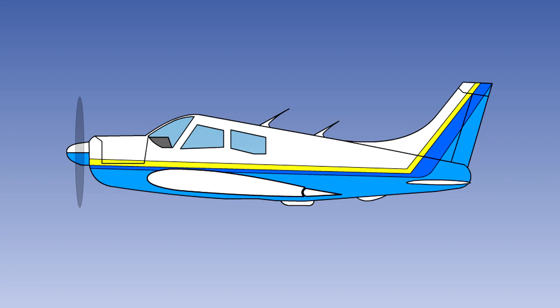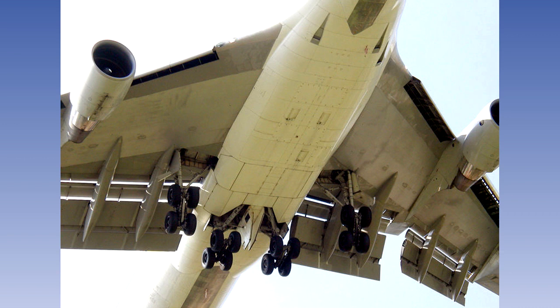The most popular type for light aircraft is the plain or camber flap, with trailing edge flaps, which are a combination of slotted and Fowler flaps widely used on large transport aircraft. This picture shows the triple slotted Fowler flaps on the Boeing 747 in the fully extended landing position.